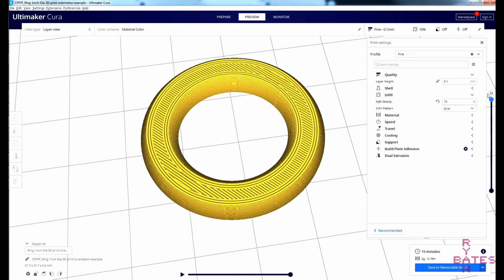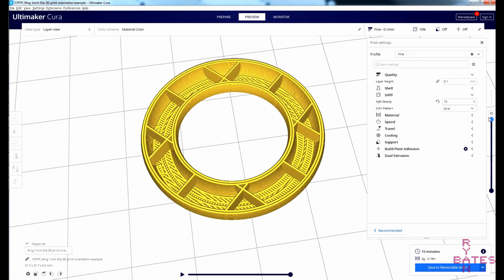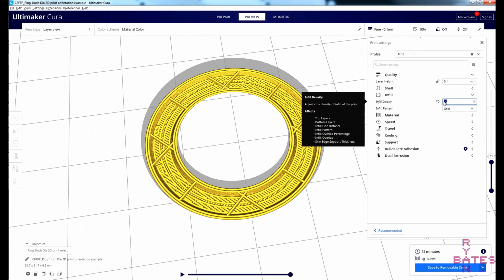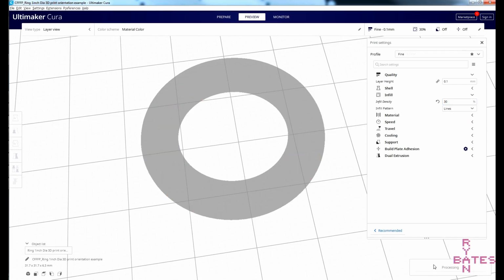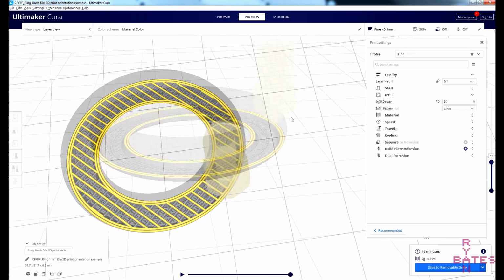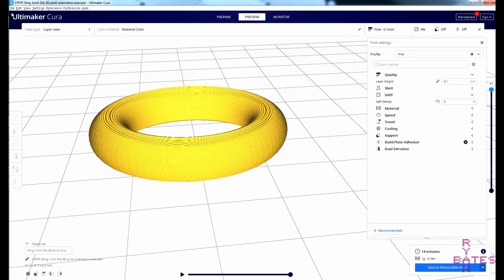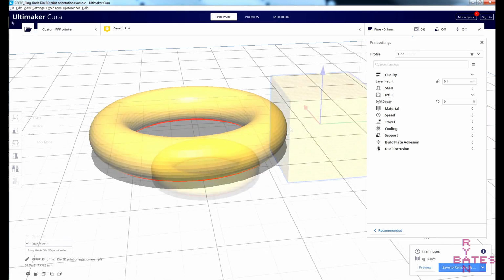Infill does have a significant influence on a part's strength, but with limitations. Remember, we can never exceed the strength properties of the filament. A mindful infill coupled with thoughtful part orientation are the best assets for strong parts. Depending on the geometry, printing a part with 0% infill doesn't usually generate great results.